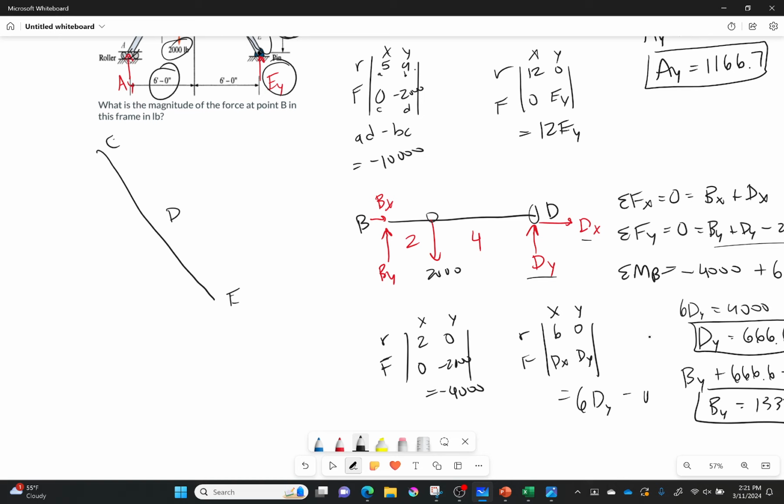I still have a point D. If you've already drawn your forces once, you have to draw them in the opposite direction. Okay, the opposite direction. You have to. If you don't, everything goes horribly wrong. As a note, whatever number I got before, it is still that same number. It doesn't change sign. It's just now pointing in the opposite direction.